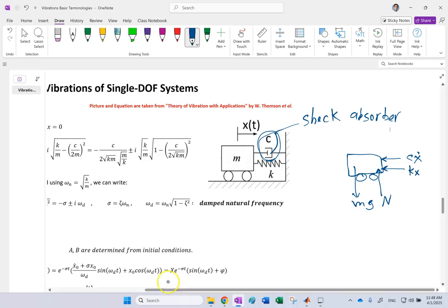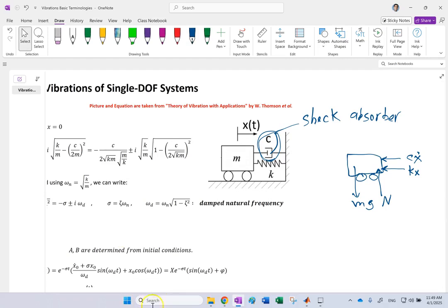That is coming from the shear forces and the drag forces from that fluid, as long as it's moving relatively slow, sometimes it could be a little bit fast too, but mostly it is for a viscous material. So for air, it's not really a big thing. For air, the drag force is really proportional to velocity squared.